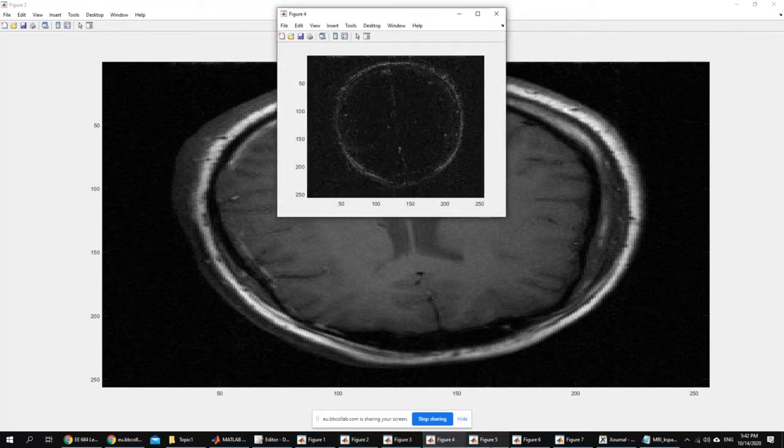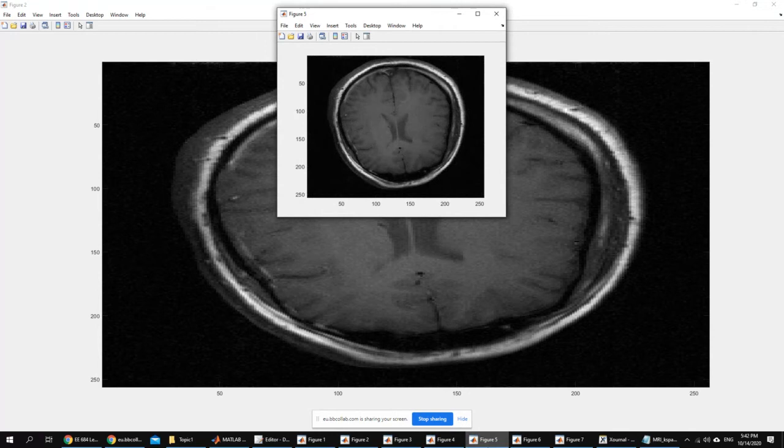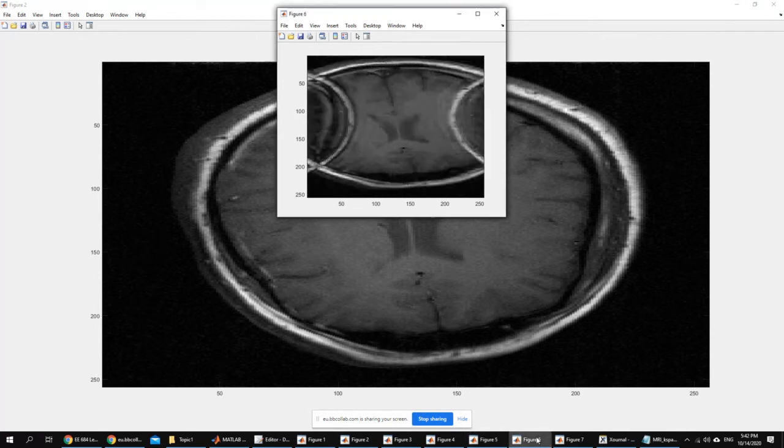Let's forget about these two for now. If you take an image and sample it the wrong way, you come out with something that looks like this. Why do we see something like this? When we undersample, you will have aliasing. Aliasing means that on the other domain, the periods will overlap.